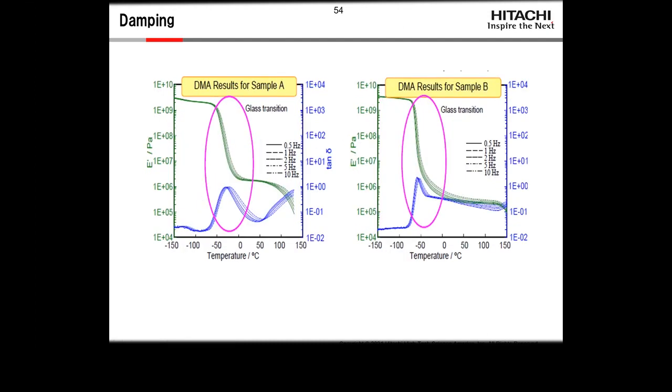Okay, damping. Damping is the ability, the tan delta, the ability to dissipate energy. And you can see here in two different materials, you get very different effects. If we are working up here in the rubbery range on both of these, this material is going to be much better at being a rubber than this one is, where the peak isn't as strong, isn't as localized. So there's a lot you can pull out on material properties from the tan delta curve too.